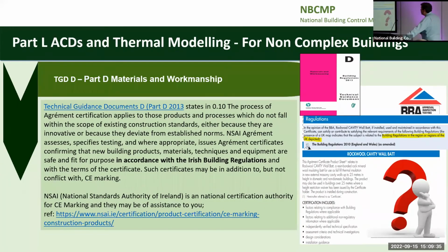This is a question we nearly get all the time. I have a BBA cert. Can I build it? So if you go to the technical guidance document D, and in 0.10, we're getting a lot of decimal places today. But the process of Agrément cert, they're basically saying that they have to be in accordance with Irish building regulations. Full stop.